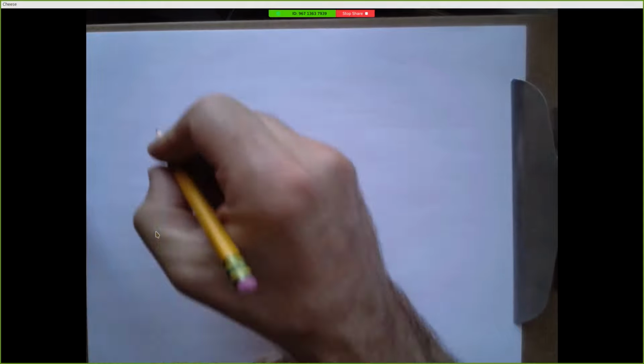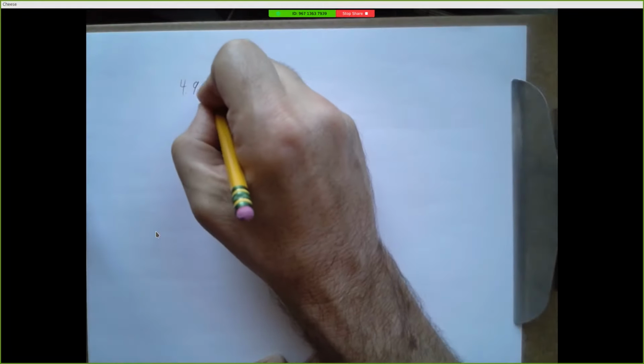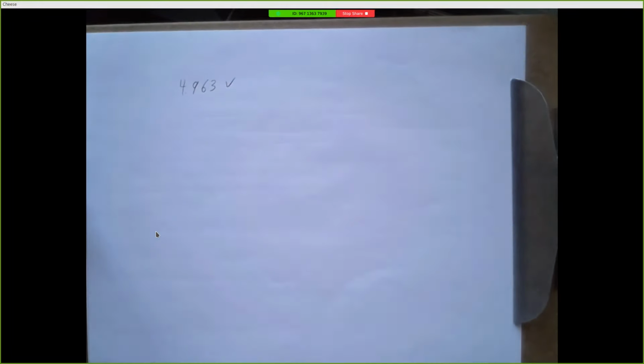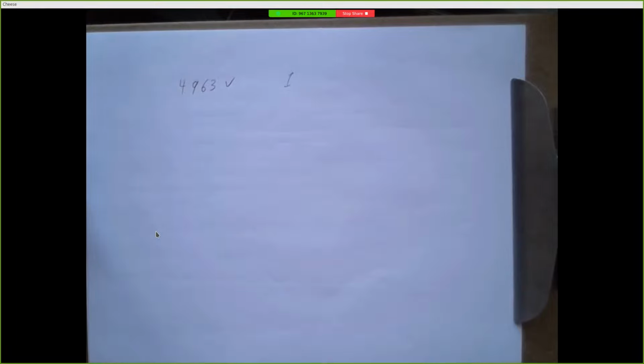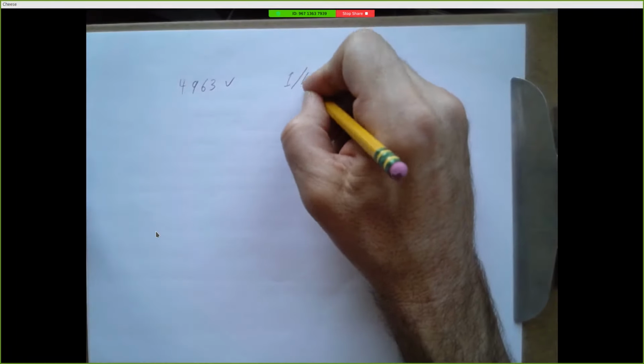But the actual world is more continuous than that, right? The voltage going into a pin is some number of volts, typically between 0 and 5 volts. But when you hook a wire up through a resistor to your power supply and you hook it up to a pin on your PIC chip, you're probably not getting exactly 5 volts. You might be getting something like 4.963 volts. And the hardware inside the PIC looks at that and says, yeah, that's a logic 1. I'm going to take that as high or true.